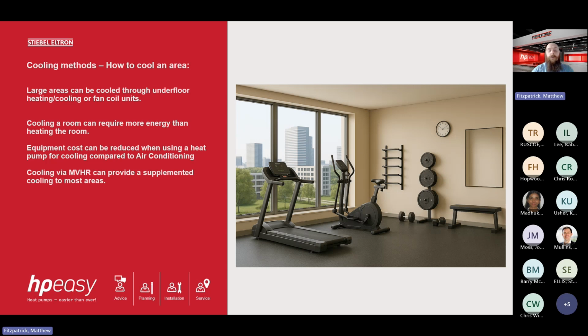Now, when it comes to sports areas and large halls, you'll normally find what are called downdraft heaters or gas blower heaters, which blow hot air around the room. When we're looking to heat or cool a commercial property through this, it may not be as efficient because we're trying to supply it at higher temperatures. It can still be done. And what we may find is we may need some more blower heaters to be installed, or a supplementary heat source, for example, additional radiators.